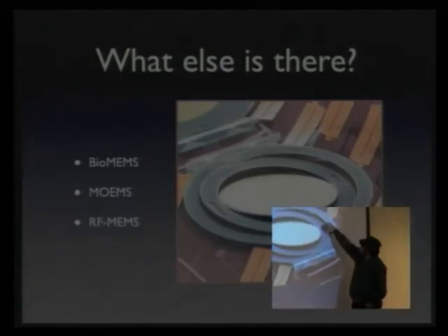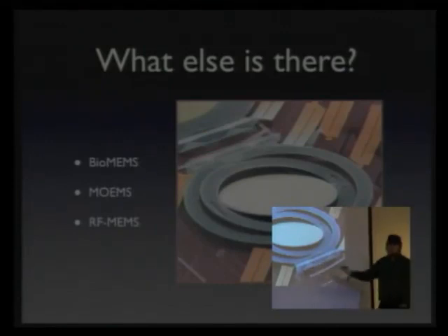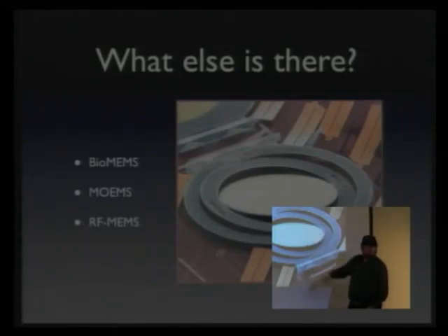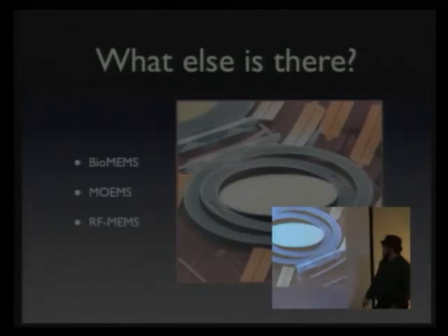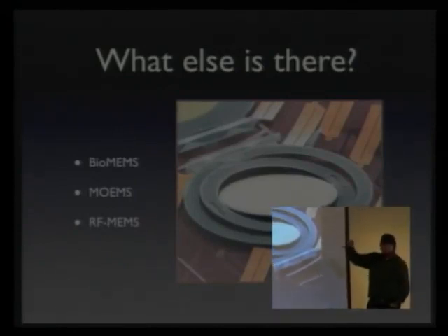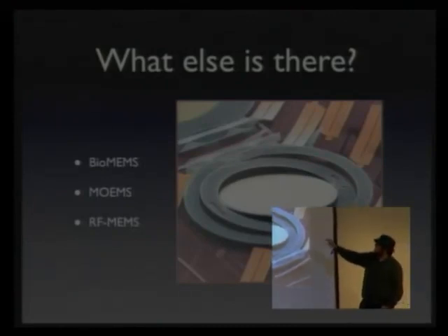So you have here some kind of springs. Here you have the mirror itself. And all the mechanics, this is not the real color of how it looks. This is colored afterwards. So what you see here is aluminum sputtered onto the surface. Sputtering is some kind of deposition process. And all the rest is made out of silicon and then folded over. And this mirror, for example, is a different one than the micro mirror array before, because this is able to move in two angles.